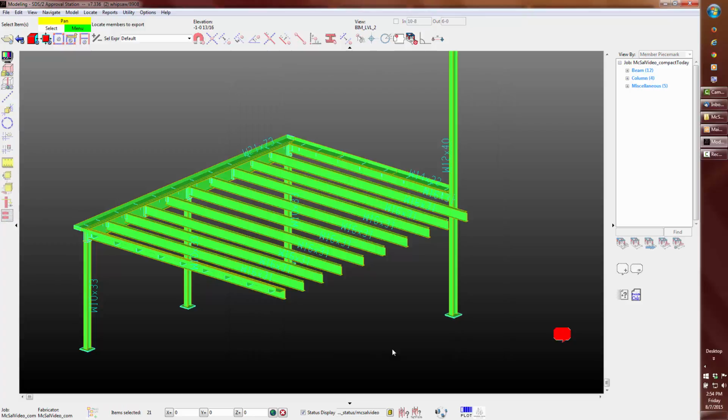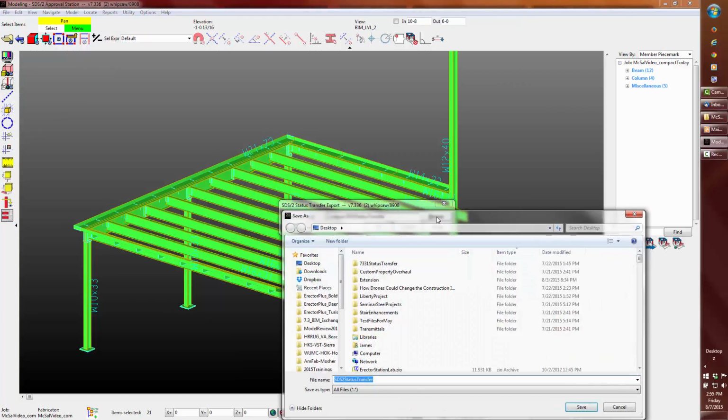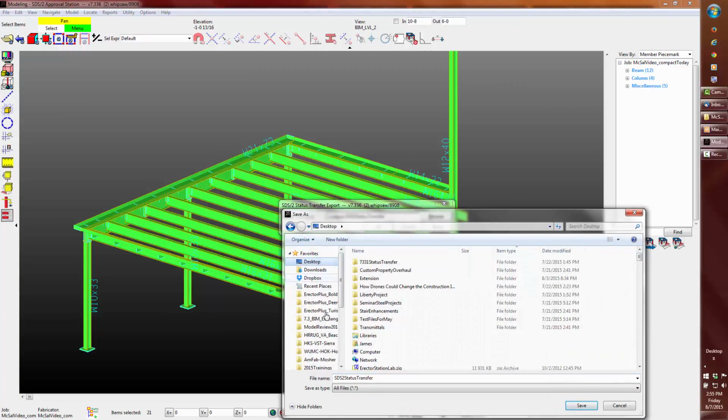The system is now prompting you to select members. I've already done that, but if you want, you can add or remove from selection at this point. Or, if you've not selected anything, you can do it now. Since I have what I want selected, I'm just going to right-click OK. Now, I will send this data to my desktop and then name the folder Submittal ABC.